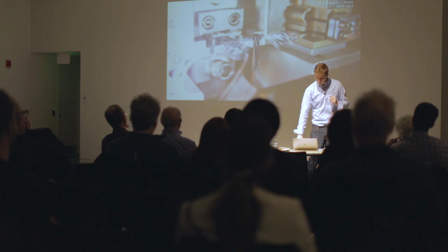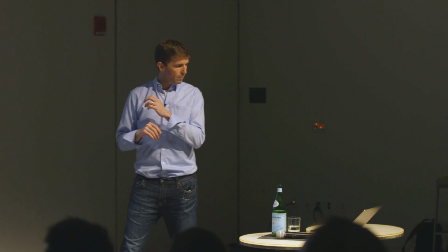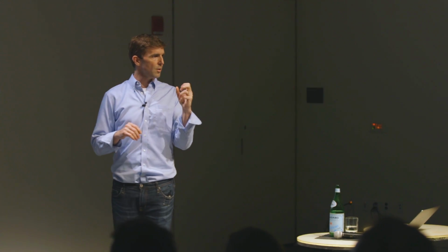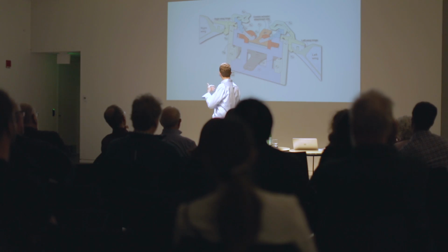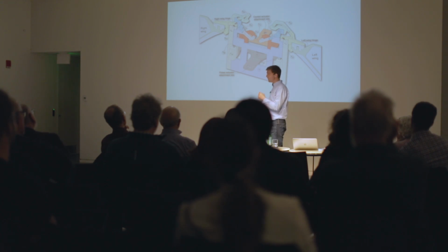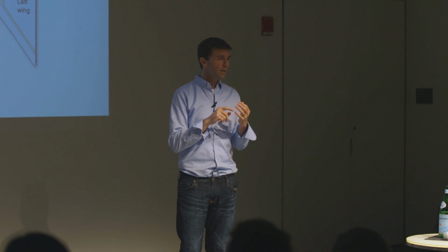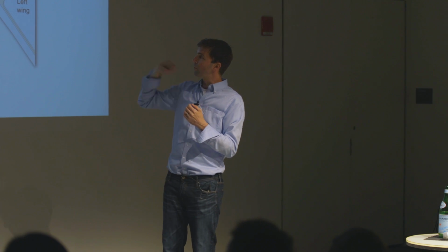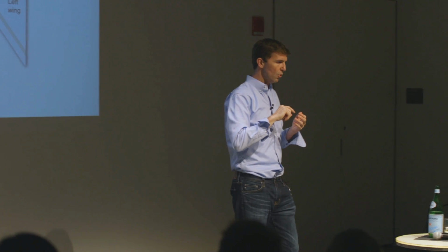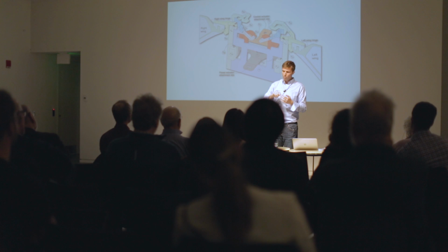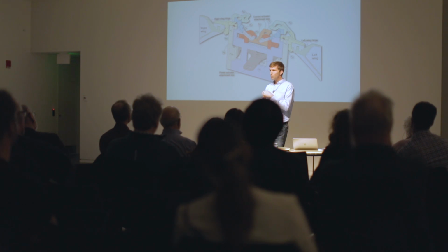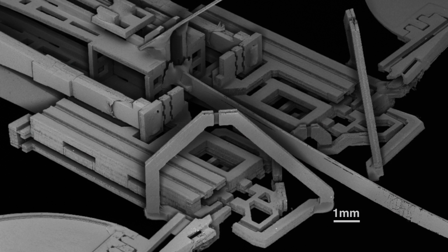I told you about how we design them. So this is an illustration of the thorax, if you will, of these devices. And this is something by a former graduate student who is trying to inject more controlled degrees of freedom in the device. In order to do this, he was adding in things like, I don't remember all the numbers here, but I think 4 parallel 4 bars, 2 spherical 4 bars, and 2 spherical 5 bars, all within a couple of cubic millimeters.